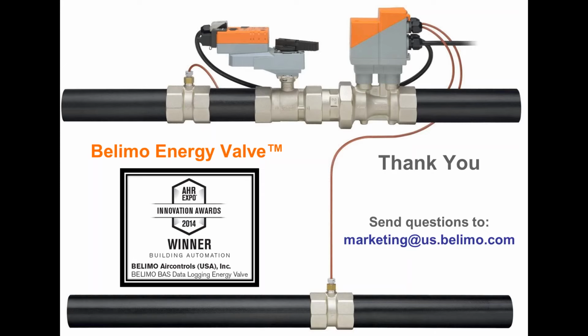In terms of laminar flow through the coil, you've got to be careful. Usually laminar flow through a coil takes care of itself because laminar water doesn't transfer heat very effectively. But I'll tell you this, it's pretty difficult to get water through everything and still make it laminar. That said, if it does turn laminar and you can't transfer heat very effectively, your discharge air will likely be disrupted. But you would have similar problems regardless of your control valve technology. So I don't know that any of this is unique to the energy valve.